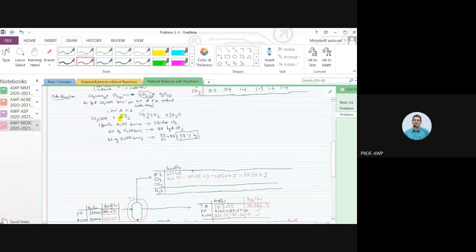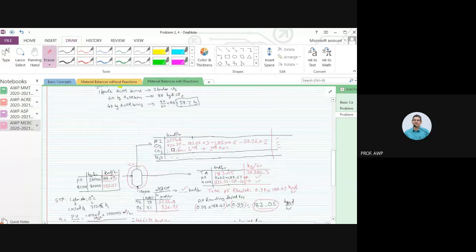So now we can calculate the carbon dioxide as well. Same way we can calculate carbon dioxide. Whatever is generated from first reaction, whatever is generated from second reaction, whatever is generated from the third reaction. Fortunately, in the first reaction, no carbon dioxide is getting generated. Carbon dioxide is getting generated only from second reaction and third reaction. So carbon dioxide generated from second undesired burning plus third reaction, acetic acid, right? Now we can find out all these compositions. Kilomoles per hour we have, now mole percent we can find out, water also we can find out. Okay, so let's just do this.